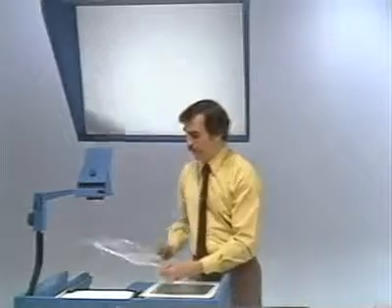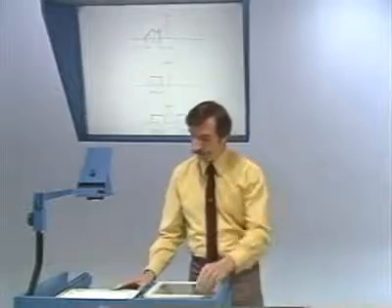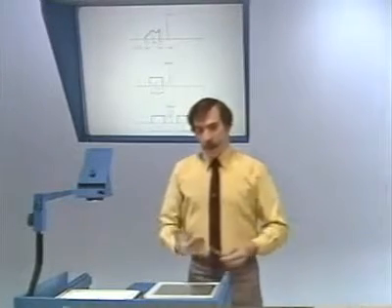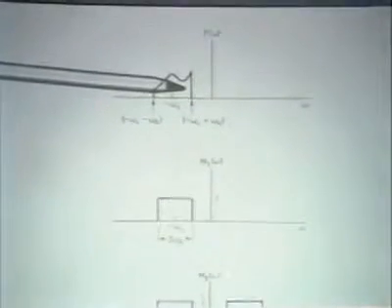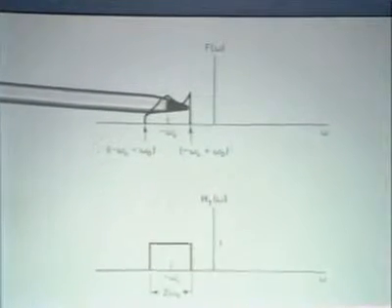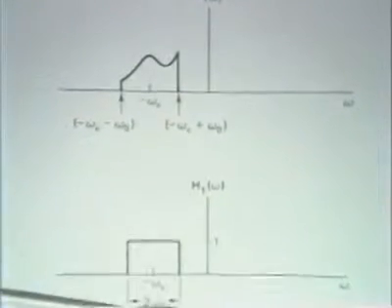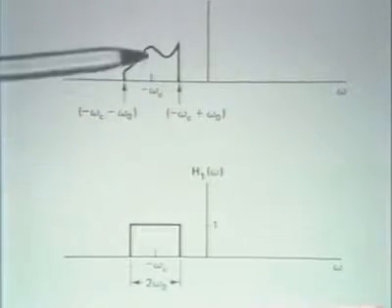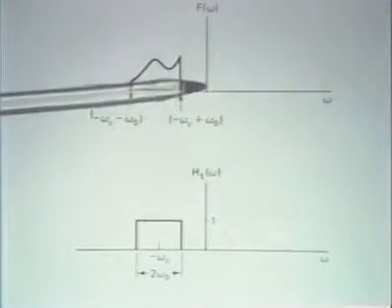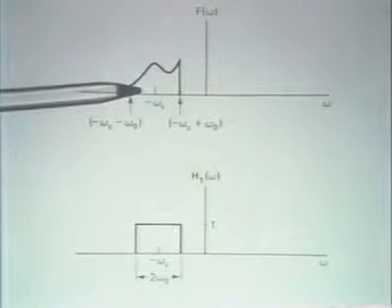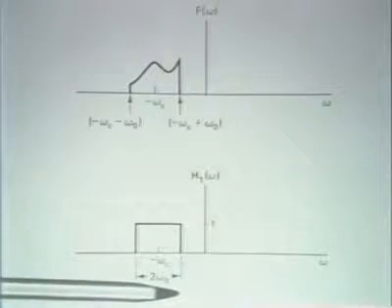So in terms of tracking through the spectrum and looking at the equivalent filtering operation, what we accomplished was to pull out this part of the spectrum using a low-pass filter and modulation, but equivalently what we implemented was a bandpass filter, as I indicate here. Now, of course, a signal with this spectrum, since this spectrum is not conjugate symmetric, we know that this signal does not correspond to a real valued signal. Equivalently, this filter doesn't correspond to a filter whose impulse response is real.